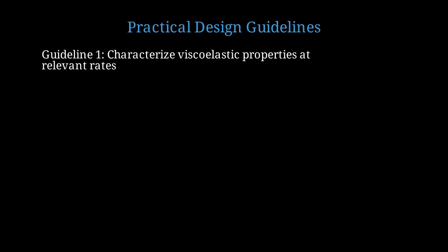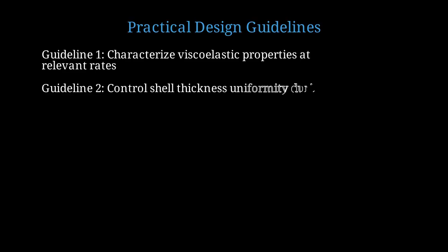Based on this understanding, I can offer practical design guidelines for creating robust microcapsules. Guideline 1. Always characterize the viscoelastic properties of your shell material at the loading rates relevant to your application. Guideline 2. Control shell thickness uniformity during synthesis. Even small variations significantly affect buckling.